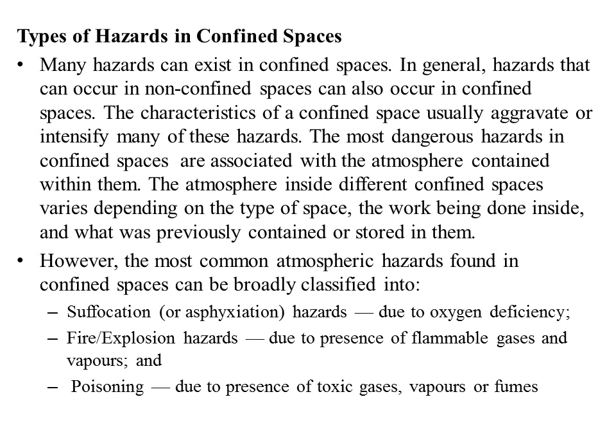However, as mentioned, there are many hazards, but the most common atmospheric hazards found in a confined space can be broadly classified into three. That is suffocation hazard. That means in a confined space there will be a lack of oxygen, which results in asphyxiation due to oxygen deficiency. A person can lose consciousness.